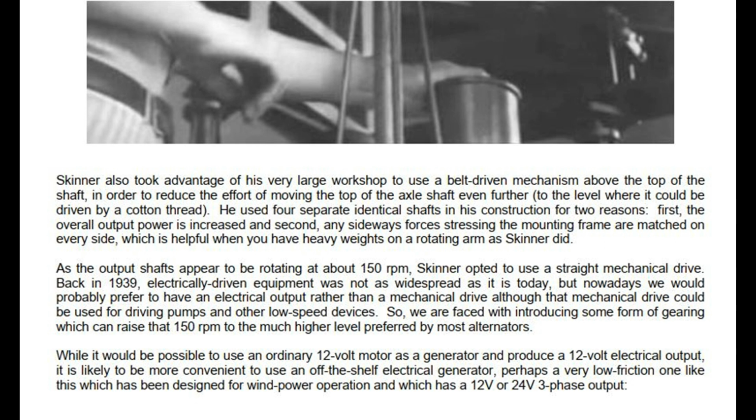Back in 1939, electrically driven equipment was not as widespread as it is today, but nowadays we would probably prefer to have an electrical output rather than a mechanical drive, although that mechanical drive could be used for driving pumps and other low-speed devices. So, we are faced with introducing some form of gearing which can raise that 150 rpm to the much higher level preferred by most alternators.